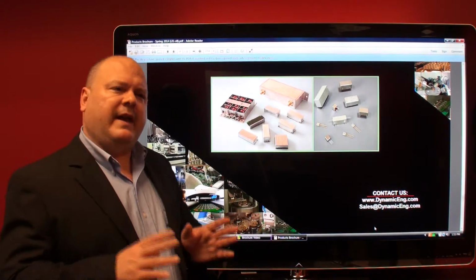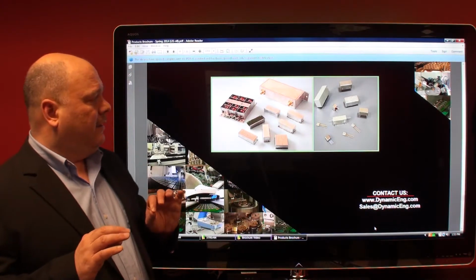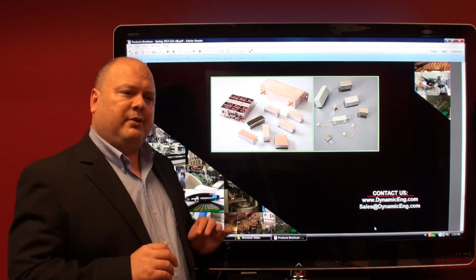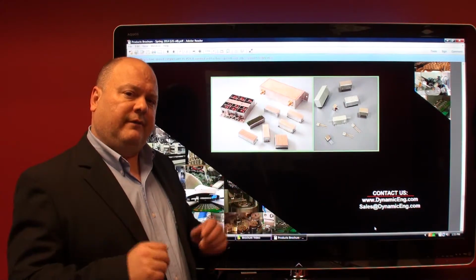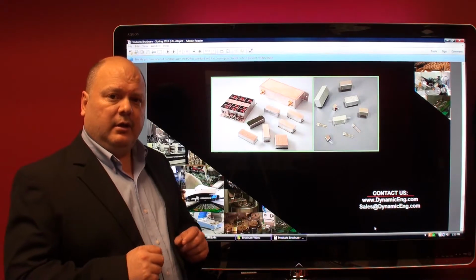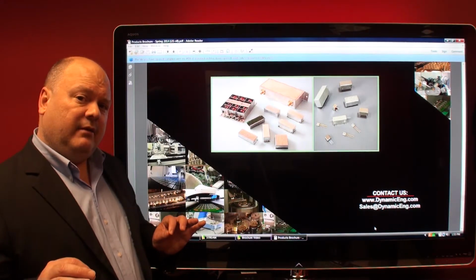We'll get more into that at a later time. But again, that's going to be for a crystal filter. You might get as high as 1% total bandwidth for a crystal filter application. For LC filters, you'll be anywhere from 2% up to 10%.